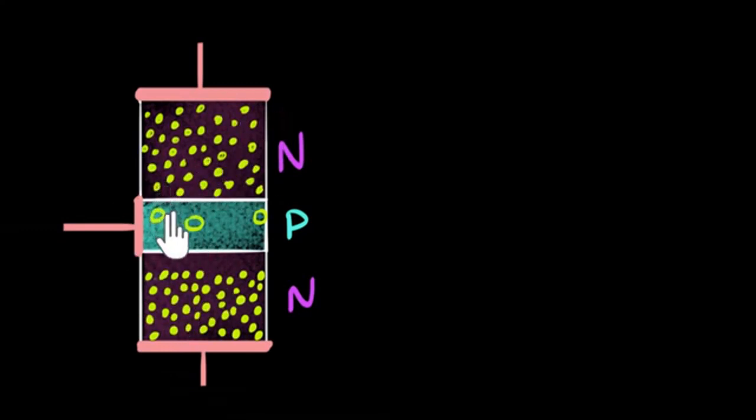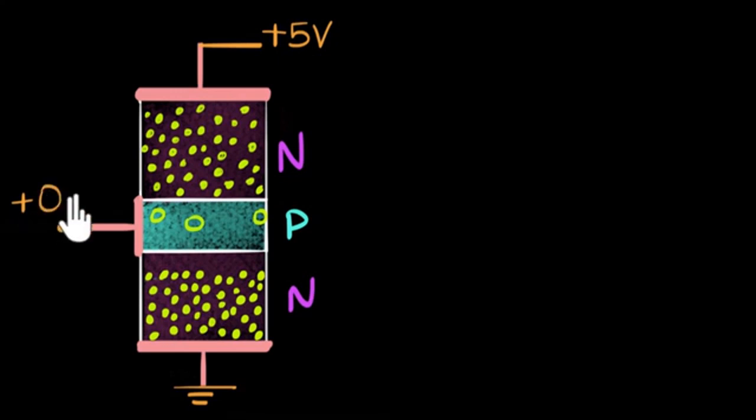In a previous video, we've seen how this transistor can behave like an amplifier. And so if you need some refresher, it would be a great idea to go back and watch that video and then come back over here. But we saw in the previous video what we did. We made some connections. We connected this side to the ground. We had connected this side to, I think, about a positive of 5 volts. Any voltage is fine here. And over this side, we had connected about positive 0.7 volt.